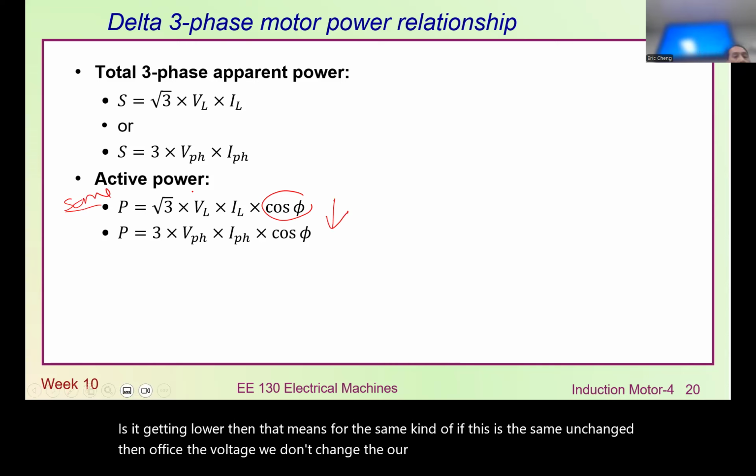And then, of course, we do have the star-connected motor. In here, we connect in star connection. You can see that our line voltage is split into two of them, and of course, they also have 120 degrees between them. So the voltage also has a root-three relationship. Root-three multiplied by the phase voltage becomes the line voltage. The current actually flows into each of the phases, so that's why the phase current and line current are the same.